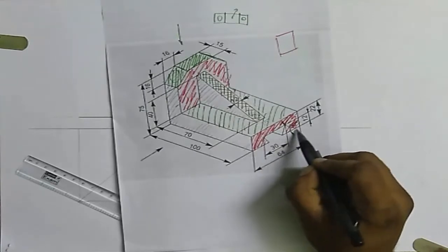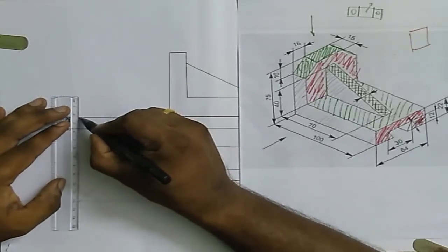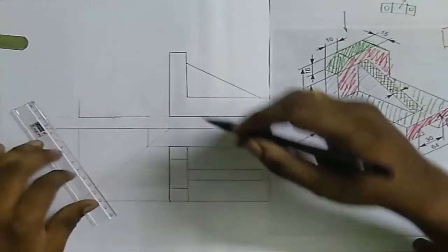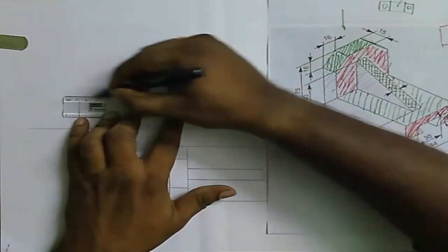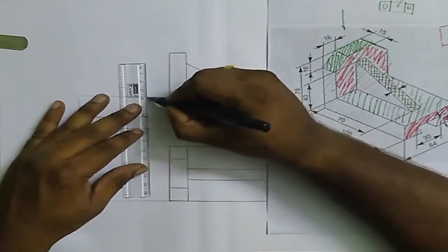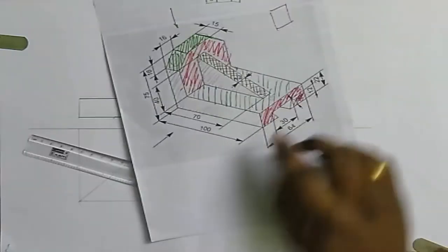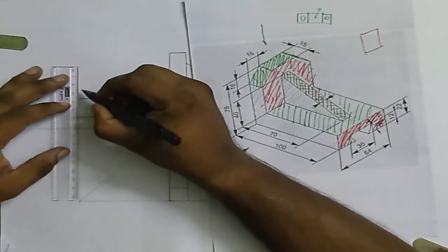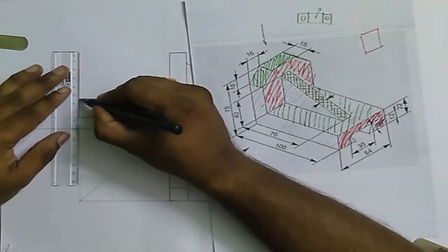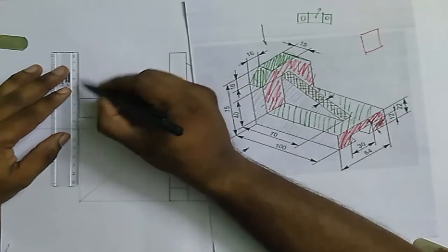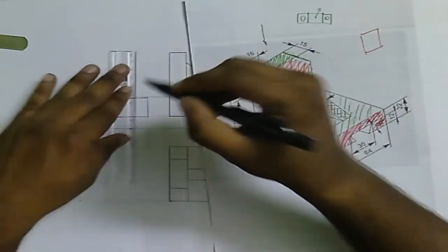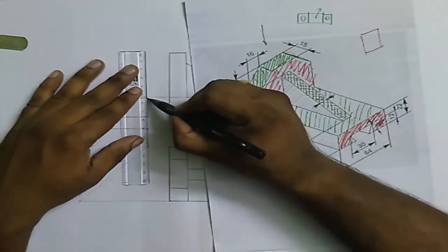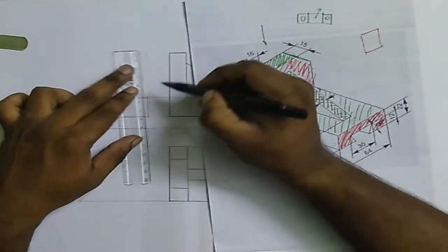Then this box has to be first completed. The thickness of that box is 22 mm. So from here make a 22 mm box or just extend this line so that you can get the 22 mm box easily. Now this box has been transferred. Now this box has to be transferred. The total height of this box from the bottom is 75. So from here it will be 53 only. So draw a perpendicular line for 53 mm and then from here also draw a 53 mm line like this.